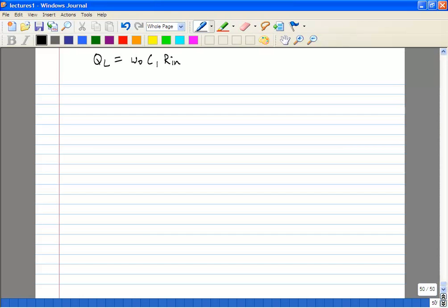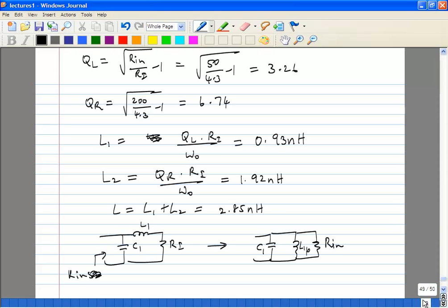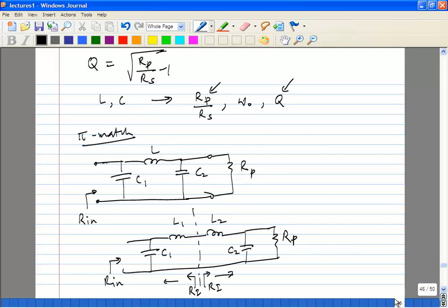Right? Yes. We calculated the inductance. So we had one series network and one parallel network. Okay. Let's go back to page 46. If you decompose, if you just look at the right side L match, you will convert it to a series RLC, and the left side you can convert it to a parallel RLC. That is right. Is that what you meant?